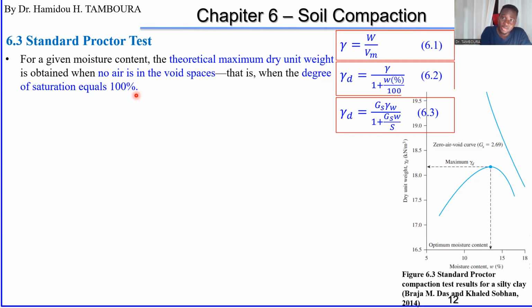When the soil is dry, with no water, it's difficult to compact. Then you add just a small amount of water. This water will occupy some void, but not 100%. Suppose that not 100% of the voids are occupied. That means the soil is not saturated. Then by doing the compaction, you will reduce the remaining voids.